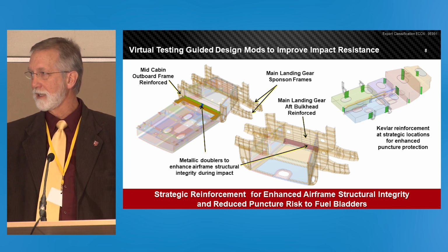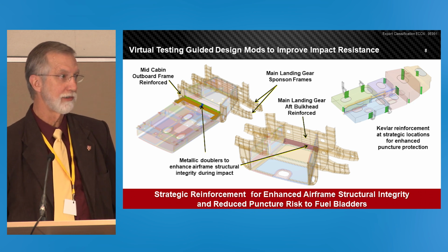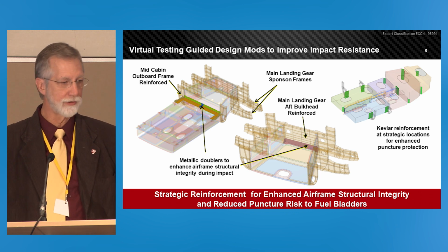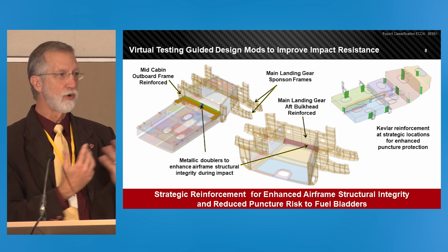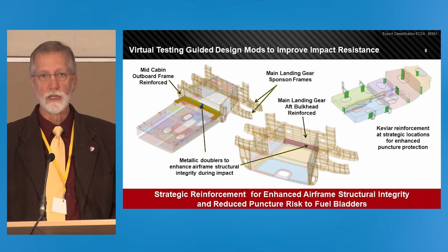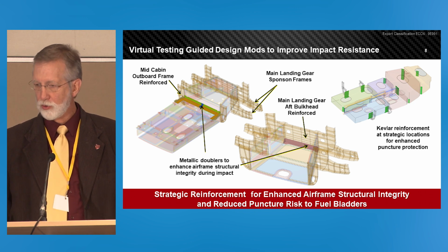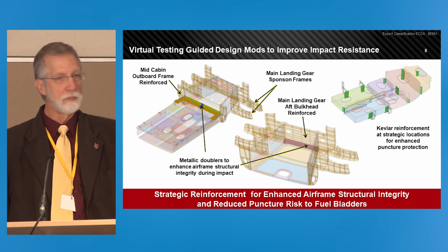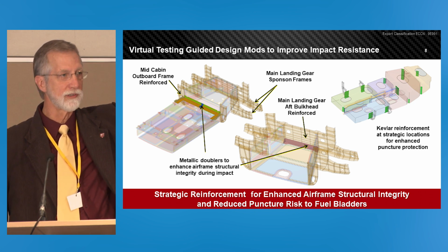It absorbs energy. So in a crash environment, plastic energy is good as long as you don't fail, or if you do fail, it's designed to do that, and you handle those sort of failures. One of the other things we discovered was that we needed to put Kevlar reinforcements over the bag areas where you had hot spots, if you will, the potential threat of puncture on the bags and things like that. So you work through the design using virtual testing to improve the design to meet the criteria to have the safety that you want for a crash-resistant fuel system.